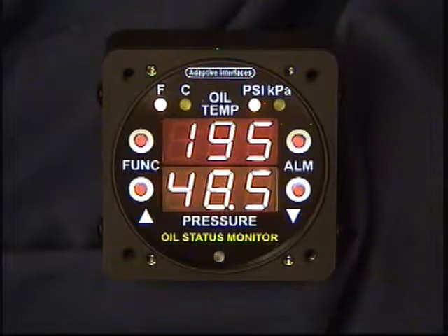Right now, the standard operating mode of the instrument is referred to as menu level 0 or the main menu. There are three other menu levels on the instrument. The first menu level will allow you to enter different options for the instrument, such as the control of the display brightness, an update value, and the selection of different types of oil pressure and oil temperature sensors. We'll get into that in a minute.